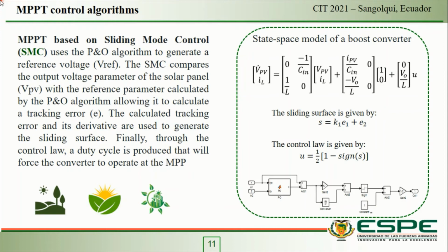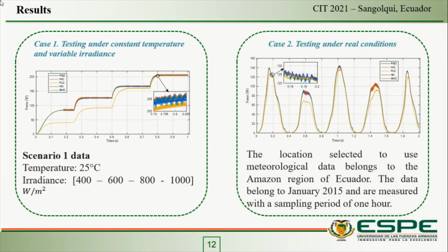Sliding mode control uses measurements from a specific solar panel to generate the sliding surface. In this research project, a variant of the PNO algorithm is incorporated to generate this surface, thus not limiting the algorithm to a single panel. Two of the simulation scenarios are presented below.